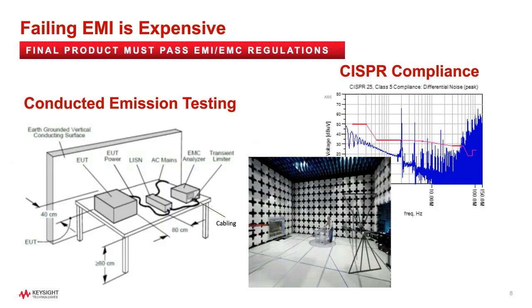Failing one of these tests at the end of the product design cycle, such as the CISPR conducted emission compliance tests shown here, can be costly. Retrofits with added filters and capacitors can add to manufacturing costs, while design respins to fix EMI/EMC problems result in product delays with daily lost revenue. It is much better to start early in the design phase to understand and mitigate potential EMI noise sources.